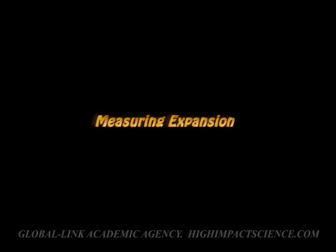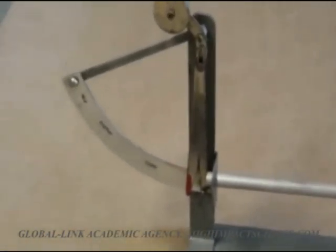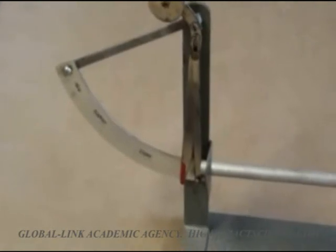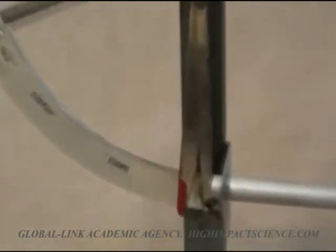The extent of expansion and contraction varies between different materials. This setup can be used to measure the expansion of various materials. Looking closely, we have a piece of aluminium whose expansion we want to measure, and over to the left we have a mechanical amplifier which will indicate the amount of expansion. A slight movement will cause deflection of the needle upwards.